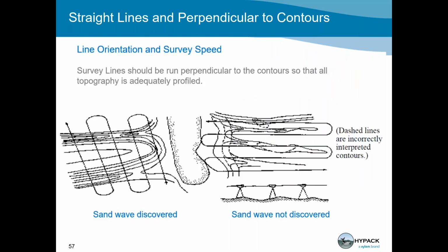All right, now that we have covered the crucial depth components to pay attention to, let's look into another aspect of single beam surveying that you need to be aware of and careful about, which is shoreline planning and also planning your vessel type. When doing your line planning for shorelines, it is always important to plan lines that are perpendicular to the shoreline. This helps to make sure that the contours will properly cover the topography around the shoreline.